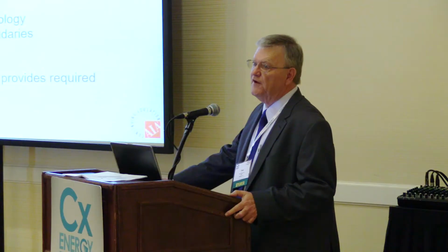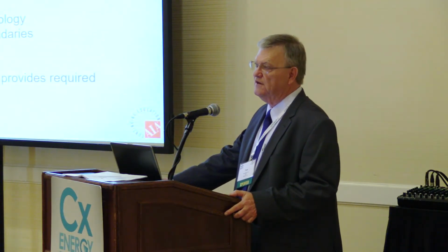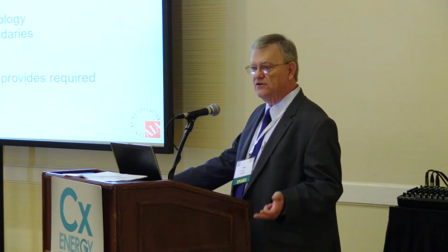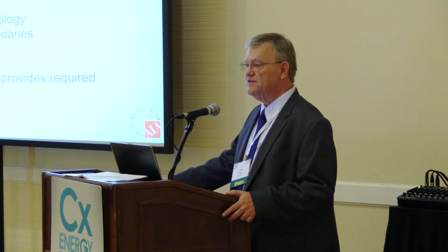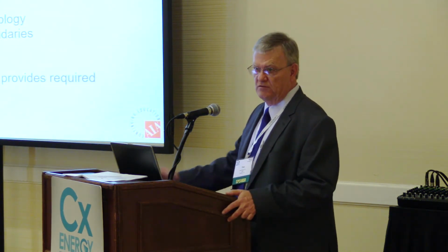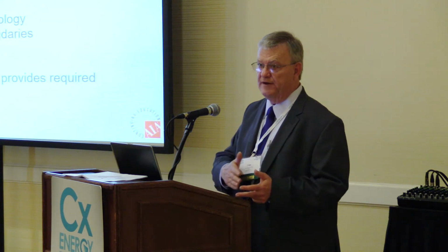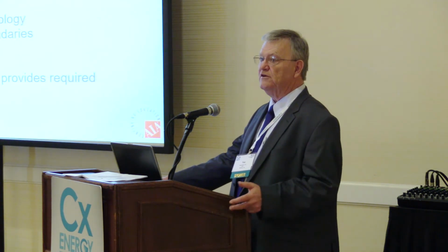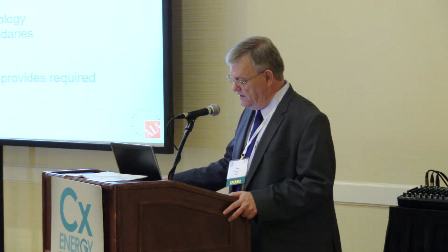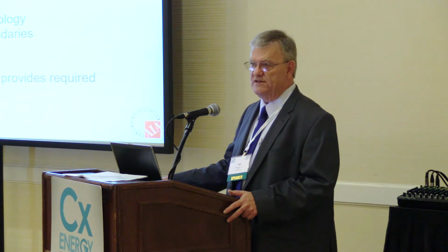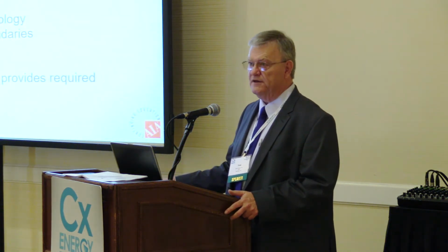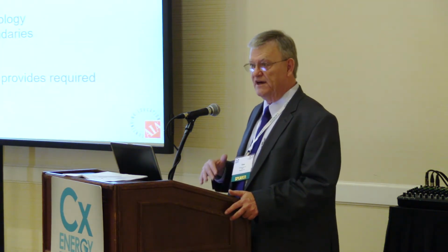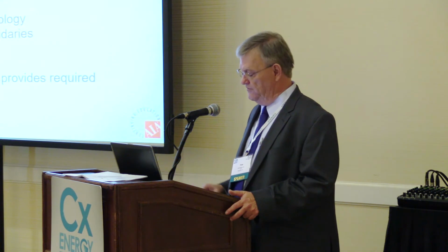We will often start with verifying the code requirements with the authority having jurisdiction, especially for a new, relatively untested code like IECC 2015. It's only been enforced in my jurisdiction for about 6 months. No large buildings have come to fruition that were permitted after November. We certainly haven't had time to build, say, a 1 million square foot structure and then fit it out. So until we know more about how these requirements actually shake out in practice, it's important to get clarity with the AHJ about the extent to which they want to enforce things and about the mechanisms that they intend to use to make sure that they're enforced.